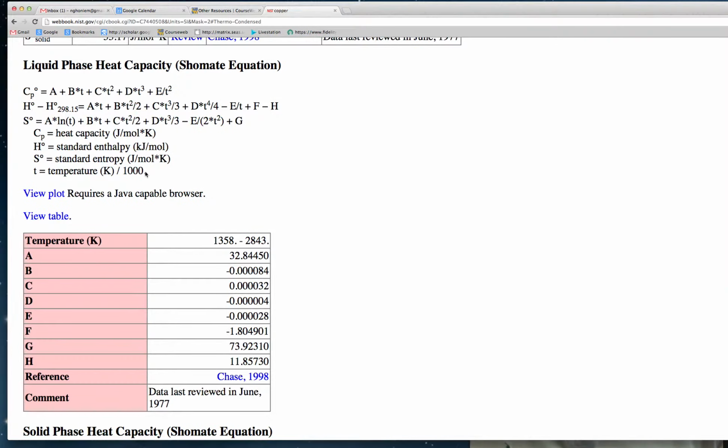These equations that you see, this is the specific heat as a function of temperature. This is the enthalpy as a function of temperature, and it is evaluated from the STP. And this is the entropy as well. And then you notice that you have these constants A, B, C, D, and E. These are constants because you represent the data in terms of polynomials.